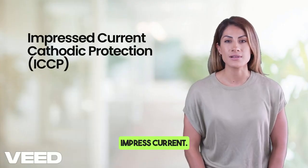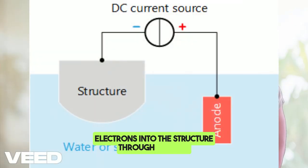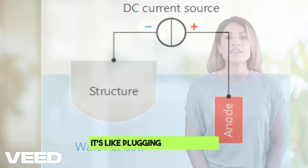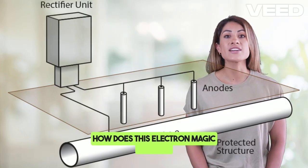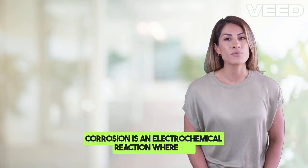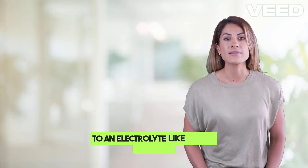Two, impressed current. A power source, like a rectifier, pushes electrons into the structure through an inert anode, like graphite or titanium. It's like plugging your pipeline into a rust-proof battery. Let's get nerdy for a sec. How does this electron magic happen? Corrosion is an electrochemical reaction where the metal acts as an anode, losing electrons to an electrolyte, like soil or seawater.